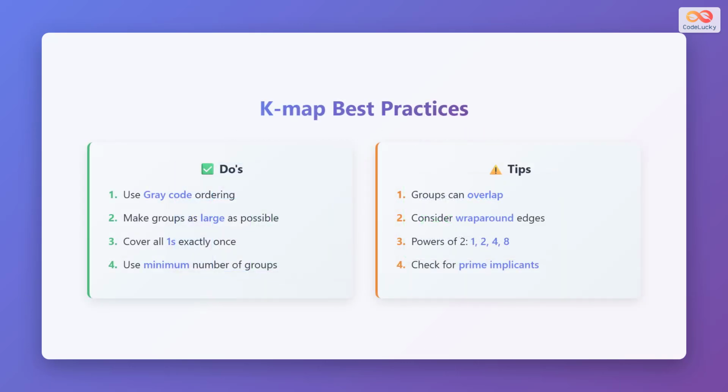Here are some best practices to keep in mind when using K-maps. First, use gray code ordering to ensure that adjacent cells differ by only one variable. Make the groups as large as possible. Cover all the ones exactly once and use the minimum number of groups necessary. Groups can overlap, which allows you to create larger groups and simplify the expression further. Also, consider wraparound edges as the edge cells are adjacent.